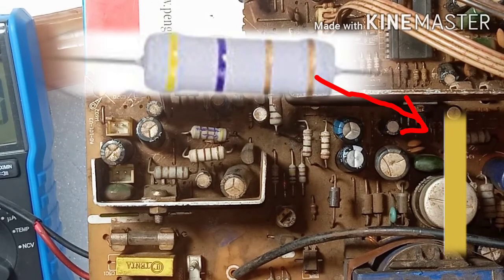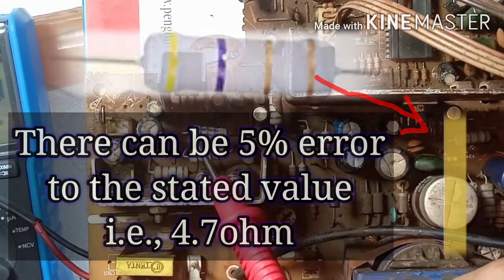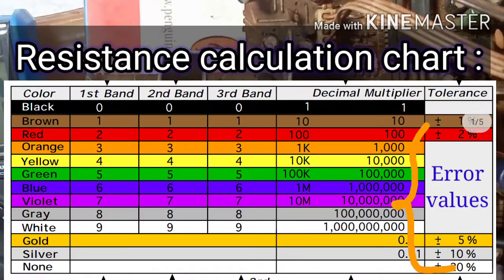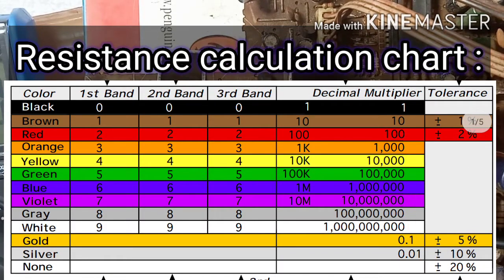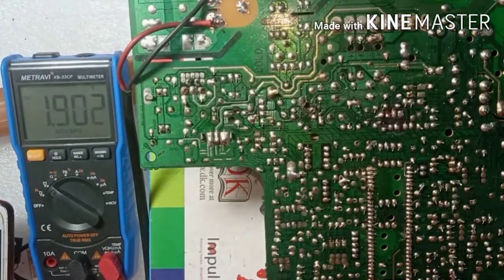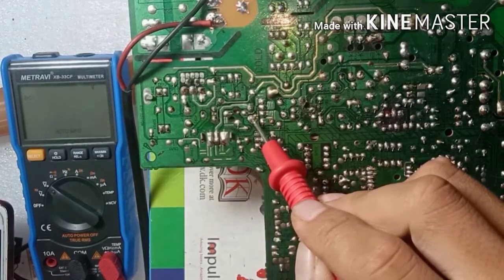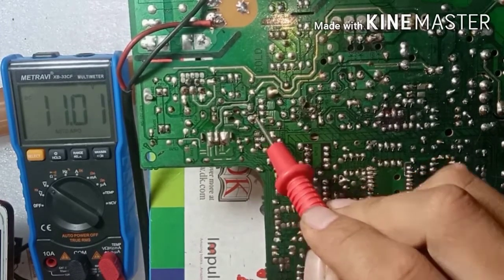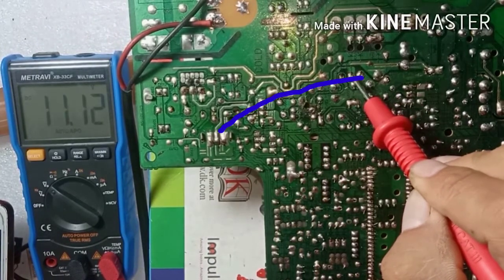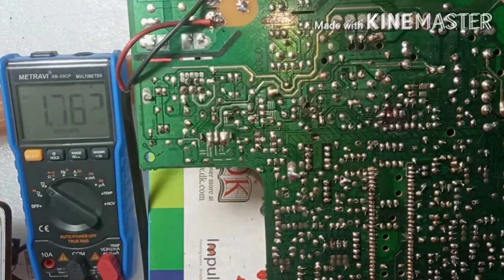And the last code is the uncertainty value. Here gold means there is an error of 5% from the stated value, that is 4.7 ohms. Because nothing is 100% efficient. You have to allow for uncertainty in every measurement you make, because measurements without uncertainties are completely meaningless. However, a 4.7 ohm resistor will never give out just around 1 or 2 volts if it is connected to an 11 volt supply line. Anyway, this 11 volts comes from here, the signal voltage that I talked about. No argument, this resistor needs to be replaced.